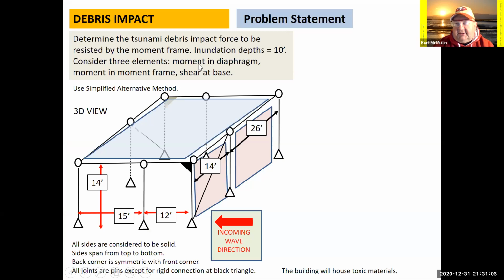And I actually want to consider three different things the engineer might be trying to determine. They may be trying to determine the moment in the diaphragm. They might be trying to determine the moment in the moment frame. They might be trying to determine the shear at the base of the moment frame.